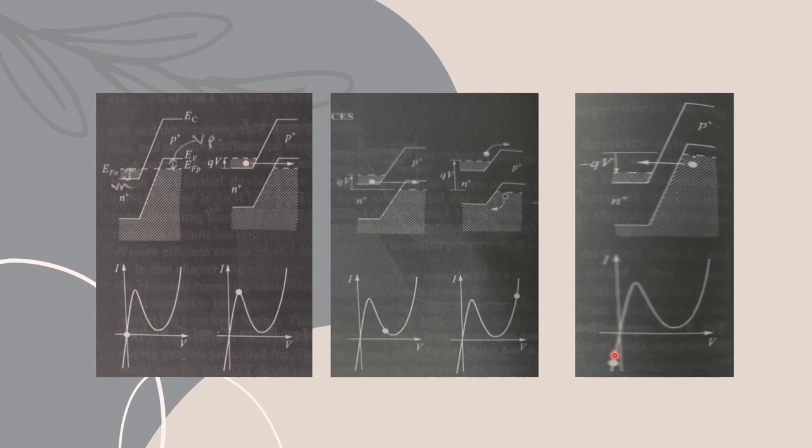When the junction is reverse biased, the Fermi level in the P side goes up relative to that in the N side. The electrons in the valence band of the P side are separated by a thin barrier, represented by the depletion region, from the available states in the conduction band of the N side. Hence the electrons can tunnel from the valence band of the P side to the conduction band of the N side.